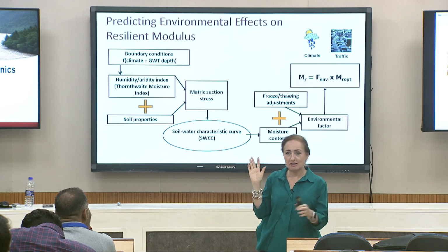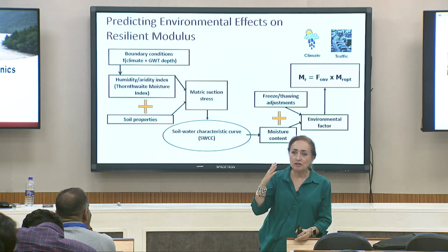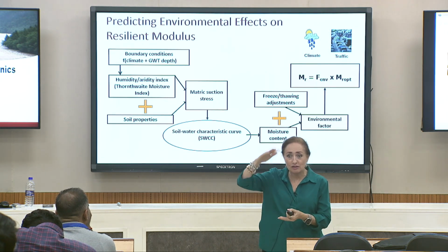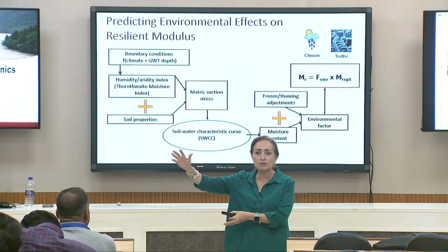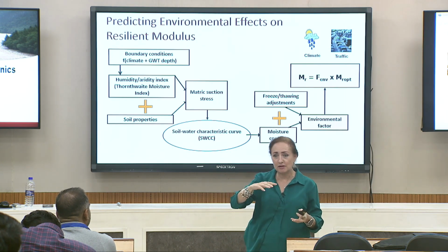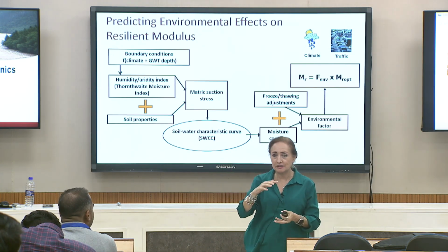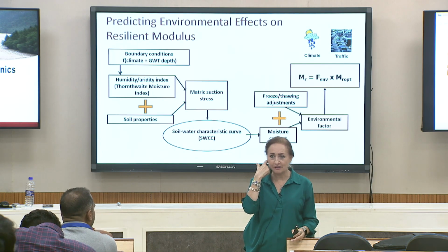This is pavement design, that is not my forte. But basically, what you do is you take all these stress conditions, and they're going to be low, medium, or high volume roads. And you're going to know what the deviator stress and the confining stress are going to be at the top of the subgrade layer. On the top of the subgrade layer, exactly.